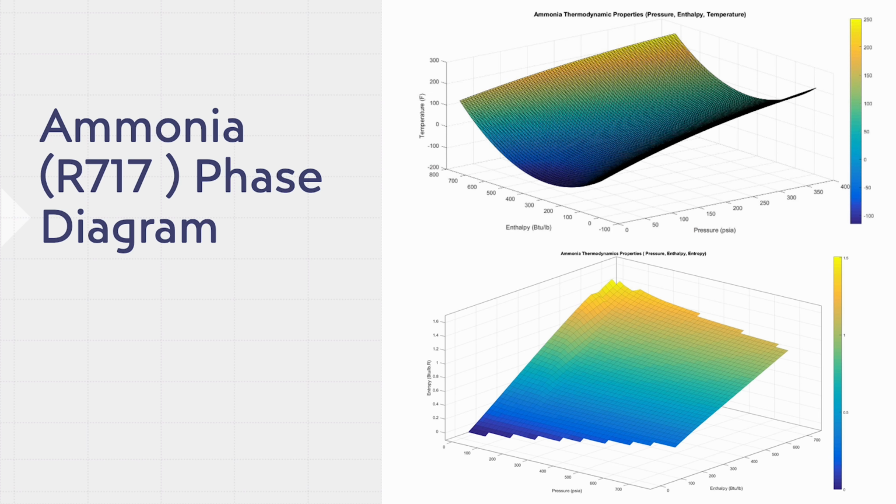And like we demonstrated on combining an equation of state with the first law to get enthalpy as a function of temperature and pressure, now we can do the same thing for the entropy as well, as we can see in the diagram below. And it's pretty redundant how we can build those diagrams. It doesn't have to be pressure, temperature, and enthalpy. It can be whatever two independent variables you would like, and then put the third dimension as whatever we want it to be. So there is nothing set in stone that it has to be only pressure and temperature.